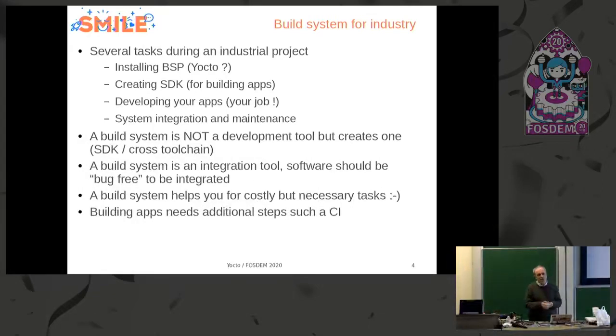But most of the time, Yocto is not a tool for development; it's a tool for integration, and development is done outside Yocto. But it's still possible, for example, to compile kernel modules and to remote debug applications inside Yocto. And developing applications needs some additional steps, such as CI, to test packages and to test an image for complex systems.